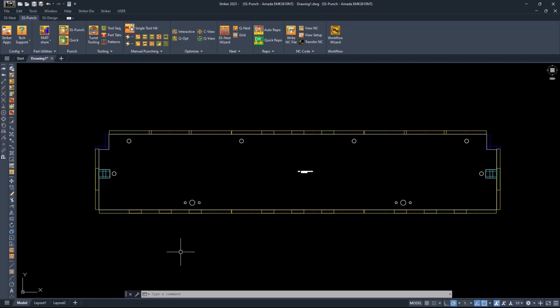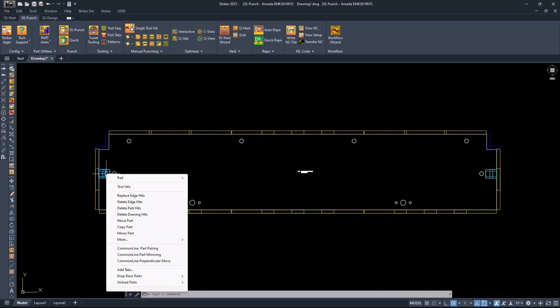And let's say that I need to fill up a sheet with this particular part. If I hover over here, what is that? That's a 1 by 1/4 inch rectangle. It's in an auto index station. Here I've got a 1/2 inch square. Well, maybe I want to use this 1/2 inch square to punch that corner out, because if I'm just running this single part, I can get rid of a tool change.